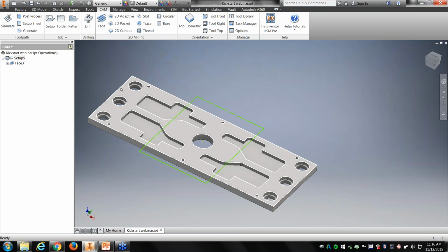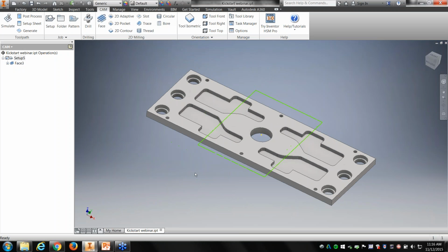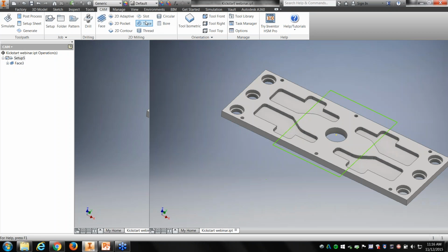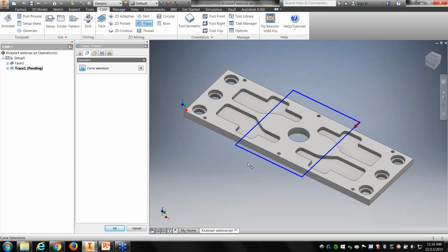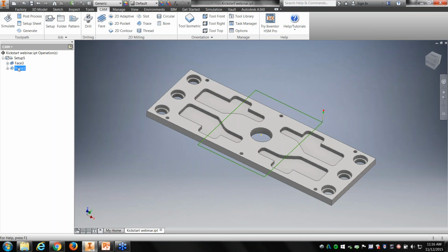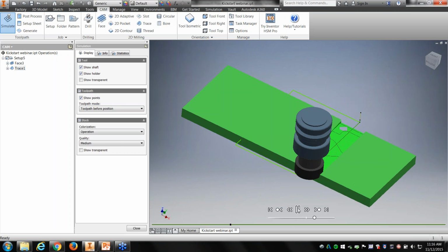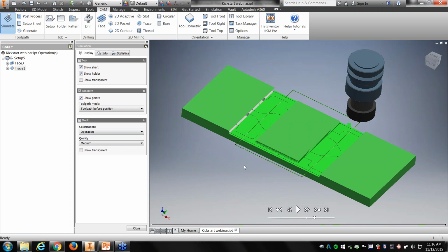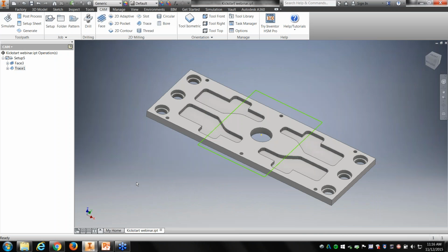And there's other ways, if you're not doing a face like this, maybe you've got a welded frame angle that you put in the mill and you're wanting to face off the top. With that model, you can do the same kind of aspect as what I did, but instead of doing a facing operation, you can actually do a trace. I'm not going to show that now, but with tracing, using the same facing operation, if I select that contour for the trace, it's going to do the center of the tool along that contour the whole time. So I'm going to do this, and I'm just going to simulate this real quick. So this would be one way, if you're wanting to reduce the amount of air cutting that might be happening, depending on the type of part you're cutting, doing this tracing operation would be another route to go.